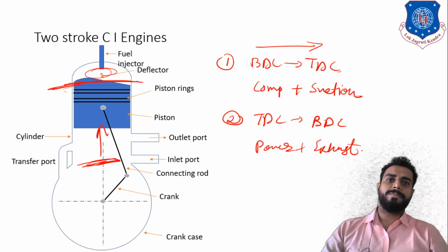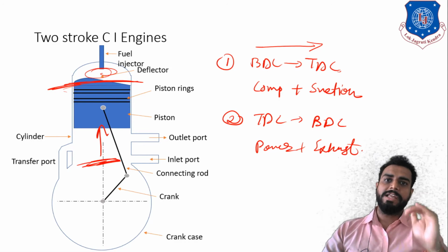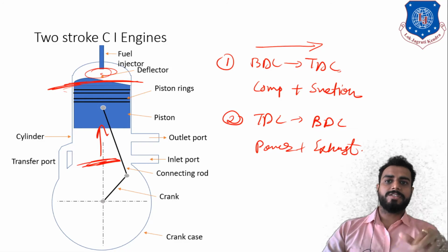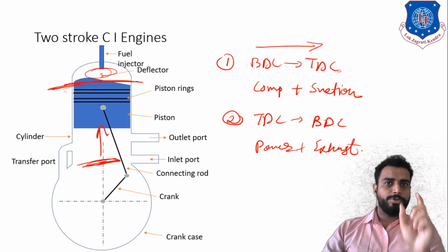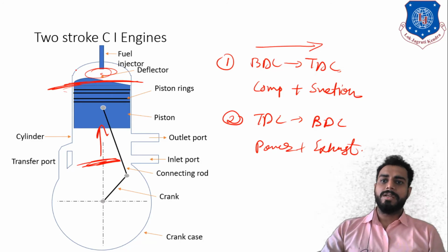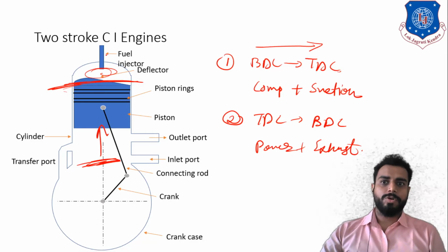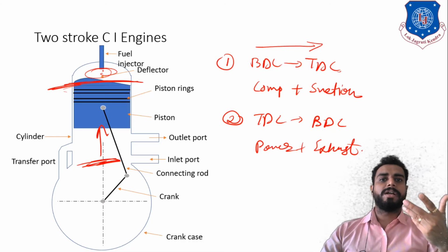That is called the self ignition temperature. Self ignition temperature means the temperature at which the fuel will ignite itself. That is called self ignition temperature, right? So that is a new term to you, understand that. In the case of diesel, the self ignition temperature will be reached, so as soon as the diesel spray occurs, it will start burning itself.